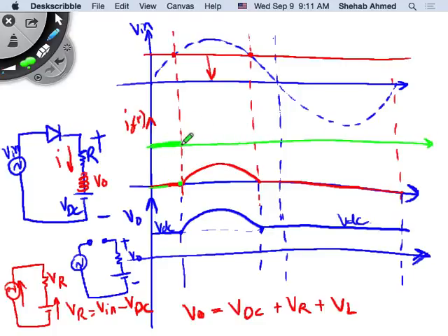That's 0. Okay, and then what? Exactly, it will rise from where the resistor current would have risen, because that's the condition for the circuit to start conducting. It will rise here exponentially. I agree. In the resistor case, the current fell here. How about for the inductor case?